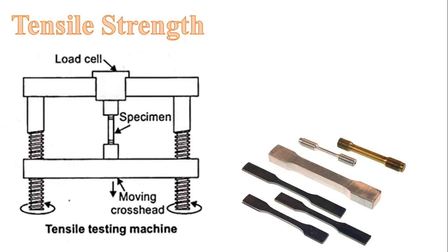The typical progress of the tensile test can be seen next. You need a special specimen of your material to run this test. Once you have the specimen made out of the material that you want to test, here's what you do. At the beginning of the test, you don't have any load. Second, you will have uniform elongation and reduction of cross-sectional area.